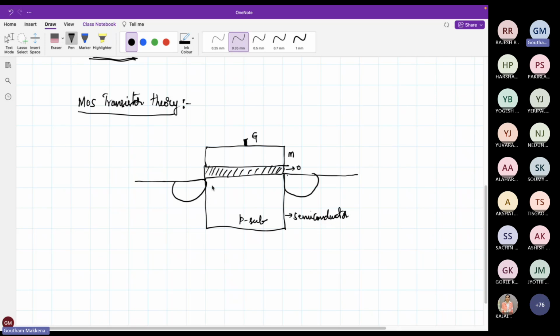Right. So what is happening? Electrons are coming here during inversion. Inversion is formed. So I take two N plus regions. What do I mean by N plus region? N-type MOS. So this is doped with N type. But why am I calling it plus?